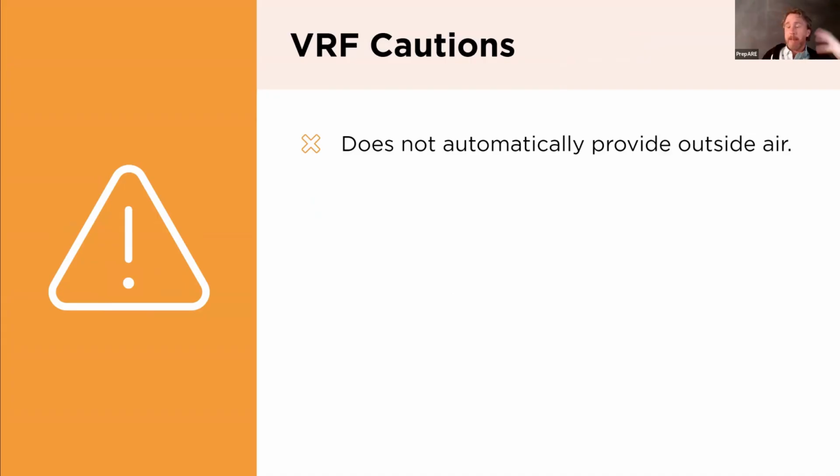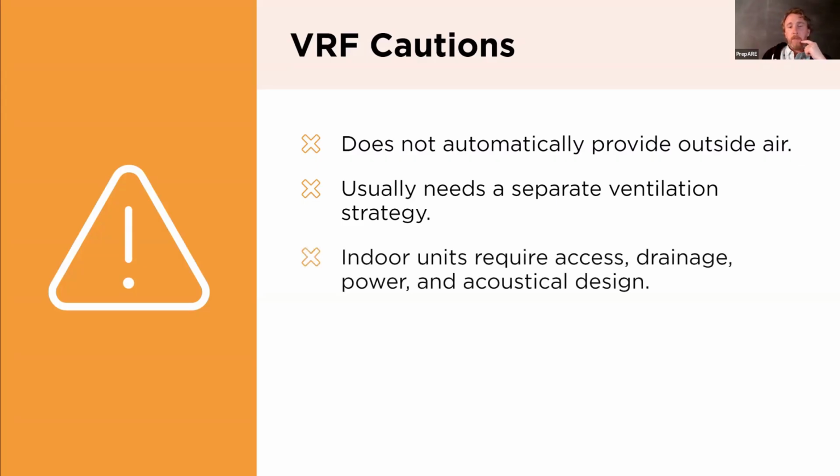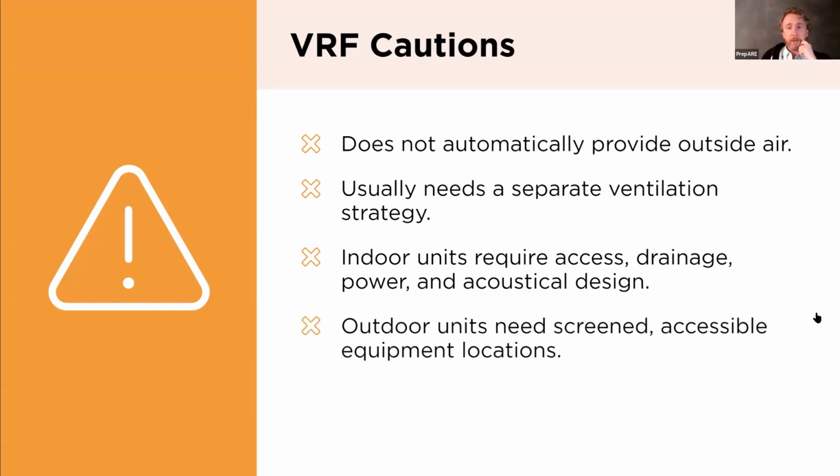So the air exchange is happening, but the VRF is just exchanging the air that's in the space and conditioning it through that unit. So you'll need a separate ventilation strategy to avoid sick building syndrome. Indoor units, of course, you'll require maintenance access, drainage for the condensate. You'll need to run power to it, and of course, acoustical design